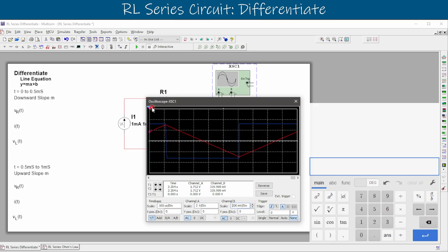From this upper peak here, we're going to watch as this slope happens. We're going to calculate the slope of that line, and evaluate what happens through the inductor while that slope is occurring. The first thing we see here is our 0.5 milliseconds, or 500 microsecond, time difference. It's negative because T2 is in front of T1, but that's okay. We can even flip those over if we wanted to.